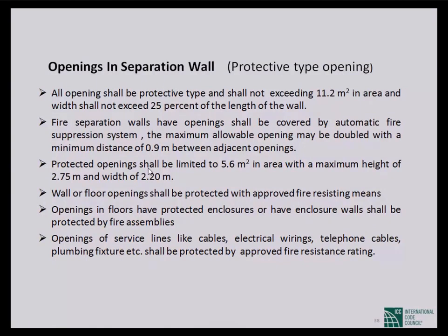So you have to understand this small opening as a penetration, or a large opening like a lift or a staircase. These are also vertical openings through the floors. So in all cases, you have to protect accordingly, with protection along the floor or protection by the enclosure.